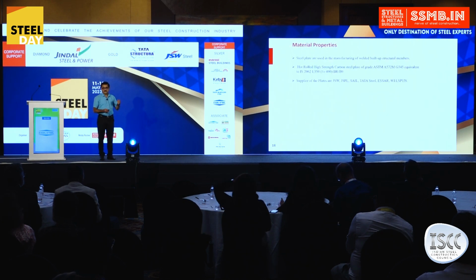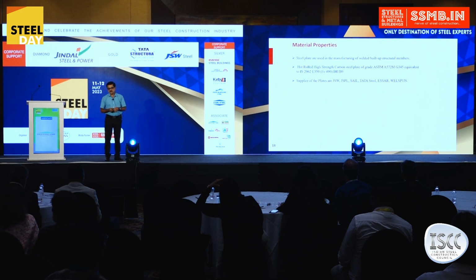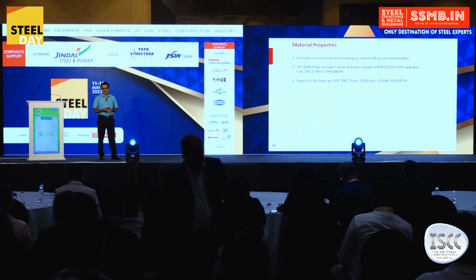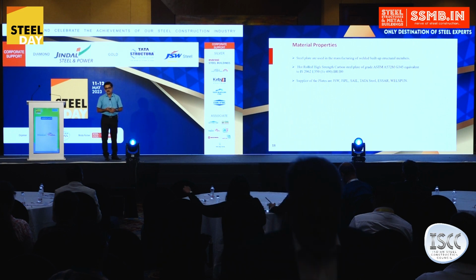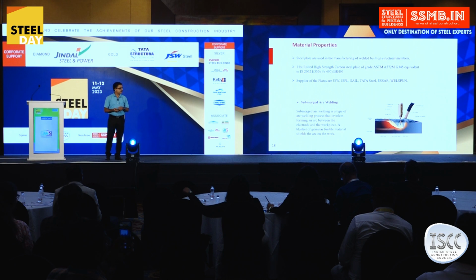While fabricating these beams, steel plates were used, which were welded to form the built-up sections. The grade of the plates was G345, which is equivalent to IS 2062 of the Indian standard. The supplier of the plates was Tata Steel, and those plates were used for the fabrication. For the welding, we have done submerged arc welding, which is seen on the screen.